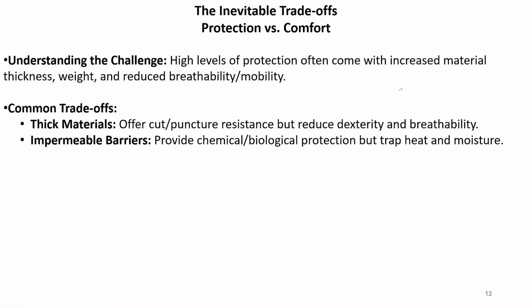The impermeable membrane is placed on a textile material; this is the textile layer, the red color layer, and over that we are using an impermeable membrane. For chemical and biological protection we may sometimes need the impermeable membrane, but the main problem is that it will trap the moisture vapor, which will not get transmitted. So, what to do?